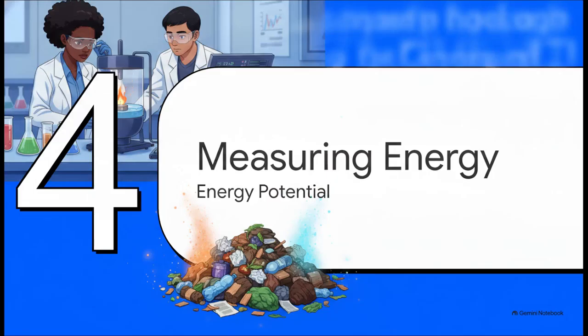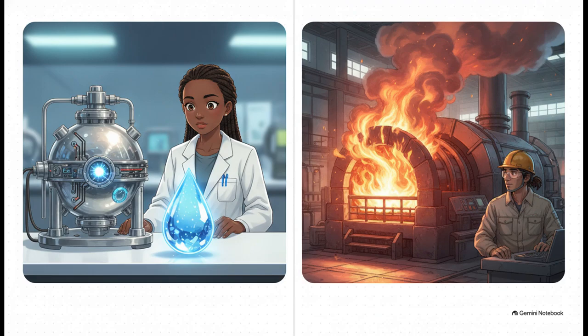All right, Section 4, Measuring Energy Potential. So we've been talking a lot about heating values, but how exactly do engineers figure out the energy potential of all this junk? Well, the gold standard for measuring heating value is the Bomb calorimeter test. In a super-controlled lab setting, a dry sample is burned, and the heat generated is measured at a constant 25 degrees Celsius. Now, because this is well below boiling, any water produced remains in a liquid state.